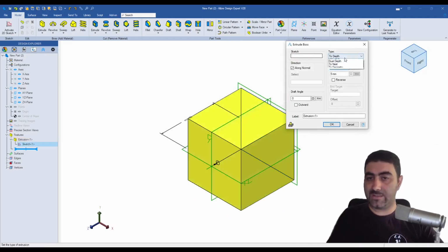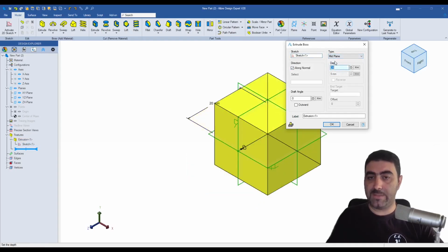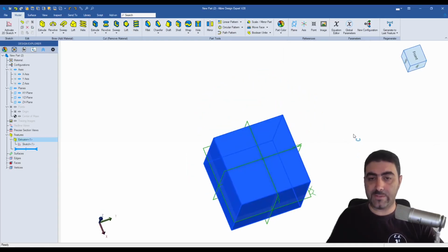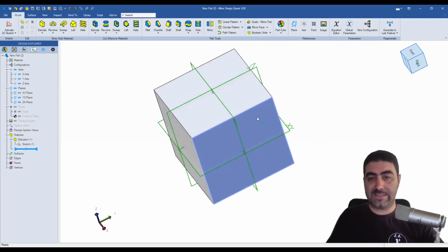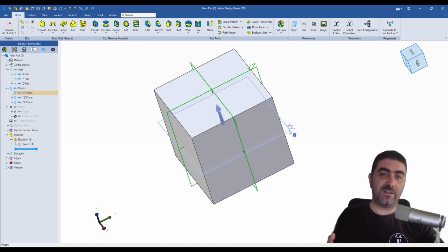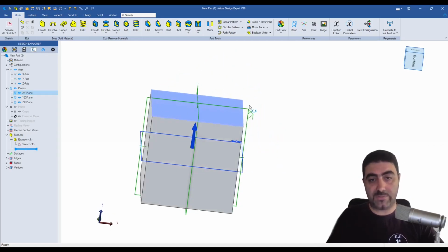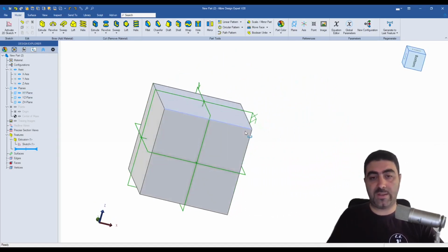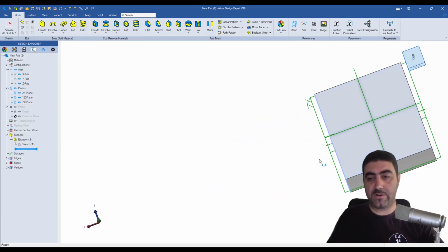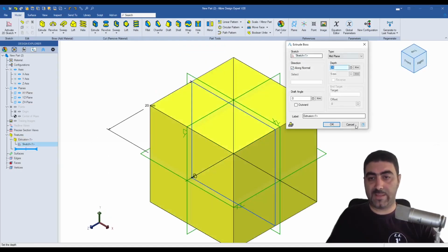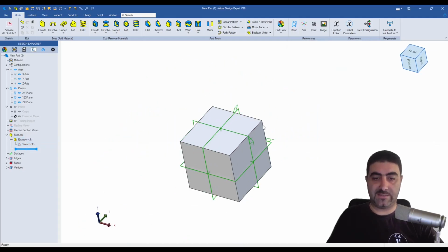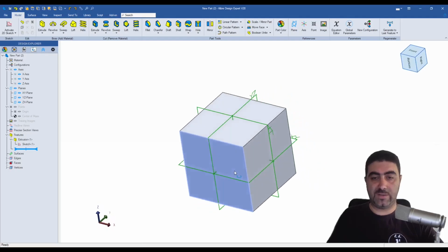And finally, look at this. Type, hit plane. So that was not a parameter, that was an option. And what did it do? It said that the plane I was designing on, the XY plane, is also a symmetry plane. So all of the three basic planes now are symmetry planes of my 3D model. And of course, playing with any other of these options and parameters will create some design intent that is then carried over to the next one.